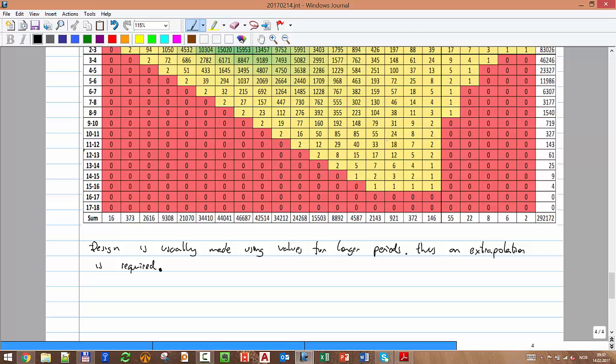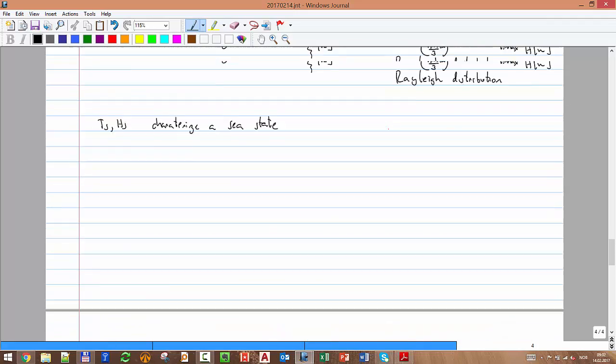Okay, wind is usually constant, doesn't change with time unless we have floating structures. Current, we take the variation with depth, but usually we consider it also constant. We have to take into account the direction where they come from. And waves are more complicated, but you use, for a 3-hour period, Fourier transform to get the peak, the frequency that has the maximum energy.